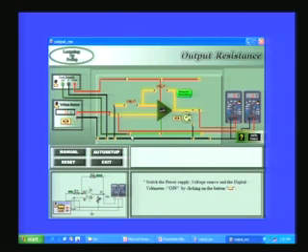Right. So, what you have here? You have an op amp connected with 10K, this is around 10K, and this is also 10K. So, I have RF 10K or RI also 10K, and that is connected to the ground.